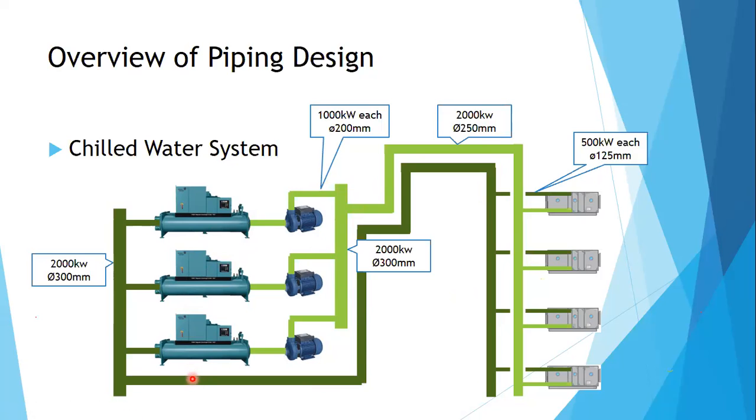If this piping is connected to here and this piping is connected to here without the pipe header, these two will have a different pressure drop or a different pressure setting. To avoid that, to make the pressure drop from this point to this point negligible, regardless of which chiller you're going to, you would put pipe headers.